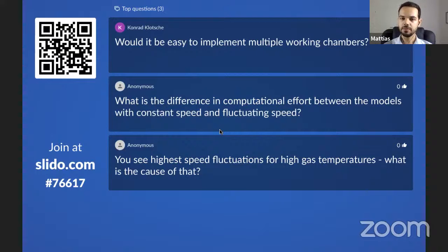So you can at the same time have a mixture of a variable torque that starts to compensate for the fluctuation, and you can even reach the ideal case, if you have a very specific torque curve versus the crank angle, where you would really eliminate all the fluctuation, and that's perfectly possible, and we did it in the software. But then there is the challenge on the electronics and motor side to really make this possible: to read how the load is coming to the compressor and react on the torque side to minimize the speed fluctuation. Okay, thank you.